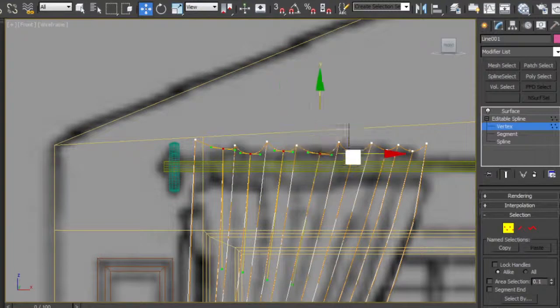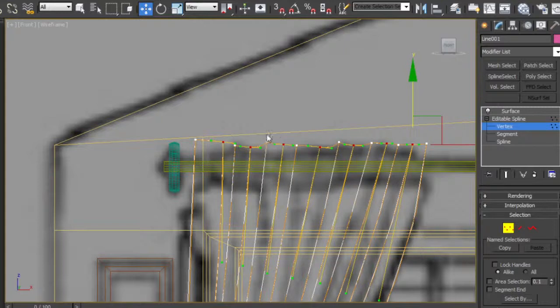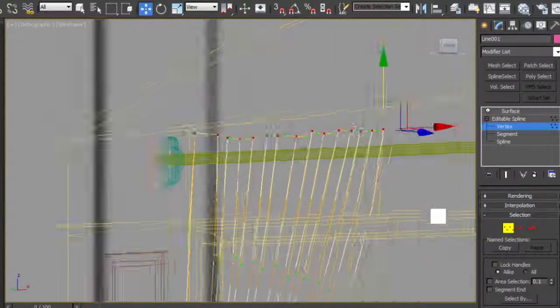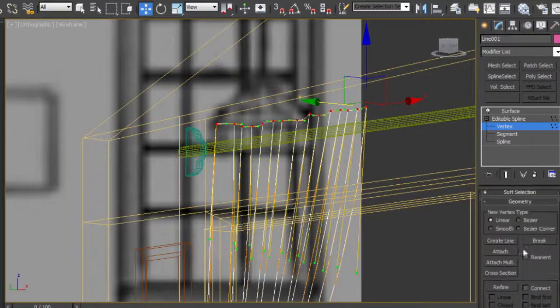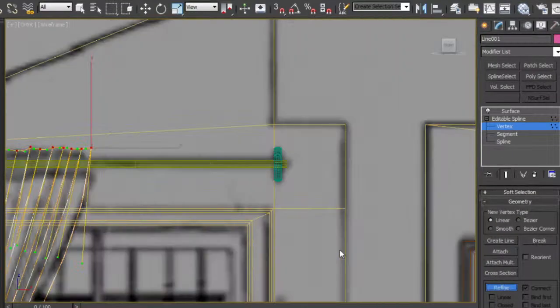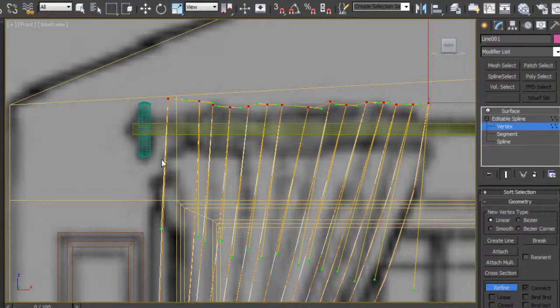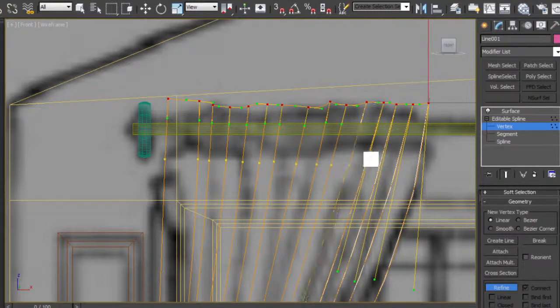It looks like there's some sort of sash work up in the top, or perhaps it's simply surrounding the form. What I think I will do here is use Connect Refine to go across the entire top. Right click.